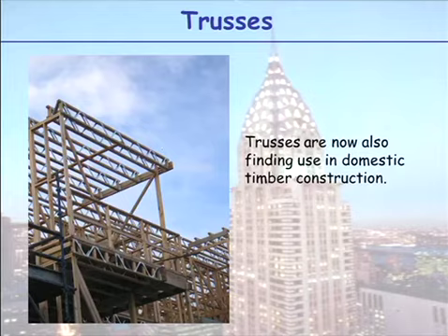Why? Well, because it's quite difficult to have big pieces of wood now. They have to laminate them together. Years and years ago, you'd cut a big tree down and get yourself a big piece of wood. Now that timber is more expensive, okay, it has become cost effective to actually make up these trusses with aluminium diagonals and timbers top and bottom. So you have them here in the flooring as well. And this also allows services to pass freely through without having to drill a hole in your section.